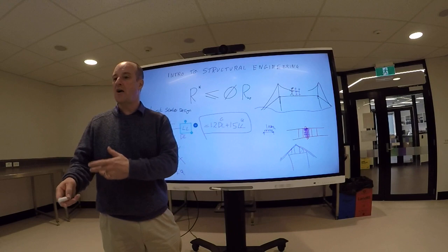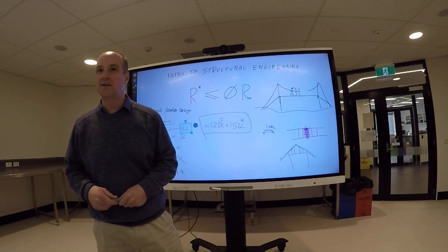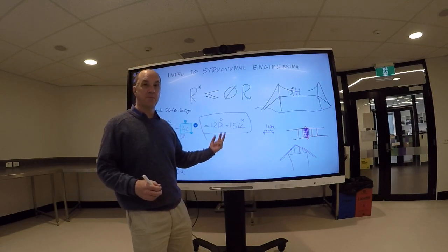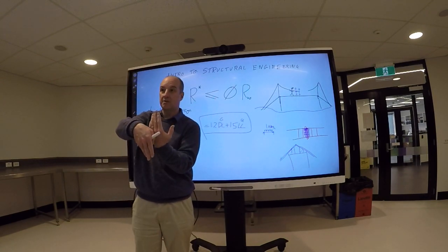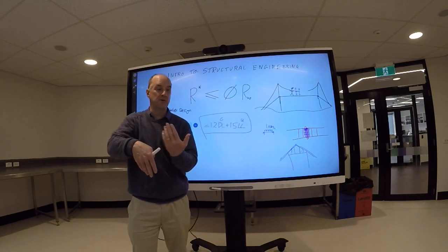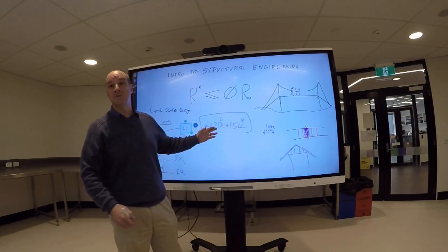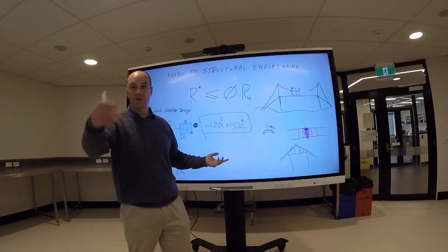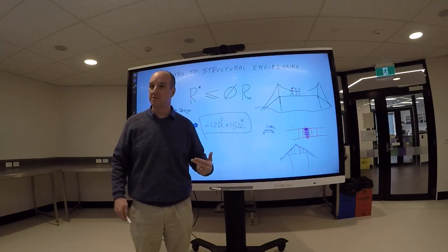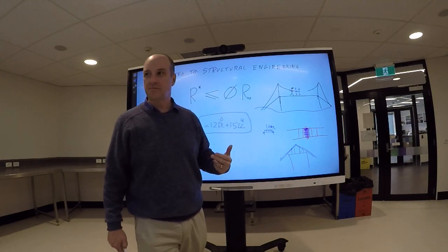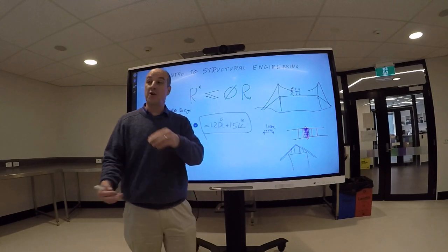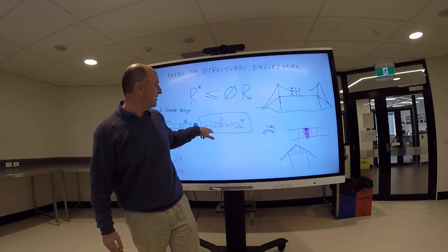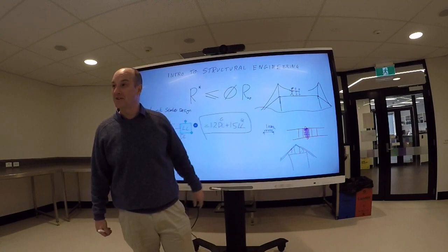Now there are subtleties and exceptions to that. For example, if the live load is something that pushes up and the dead load is pushing down, they work in opposite directions. So in that case, you go 0.9 times the dead load and 1.5 times the live load, or 1.2 times dead load and 0.9 times the live load. Don't worry about it. If they're going in opposite directions, these factors change. But basically for gravity, that's your factor there.